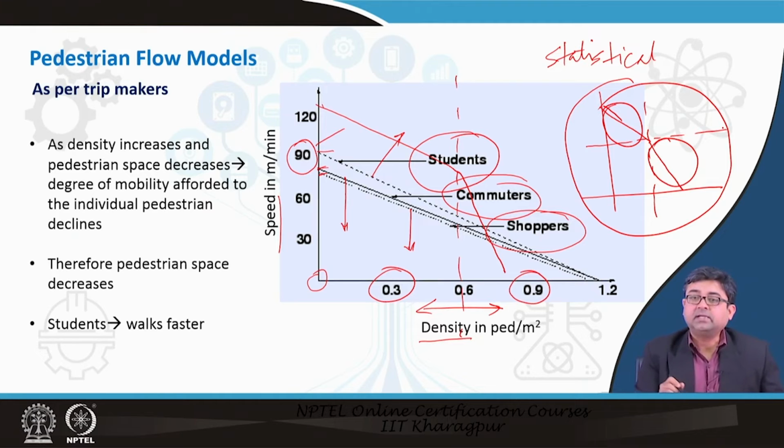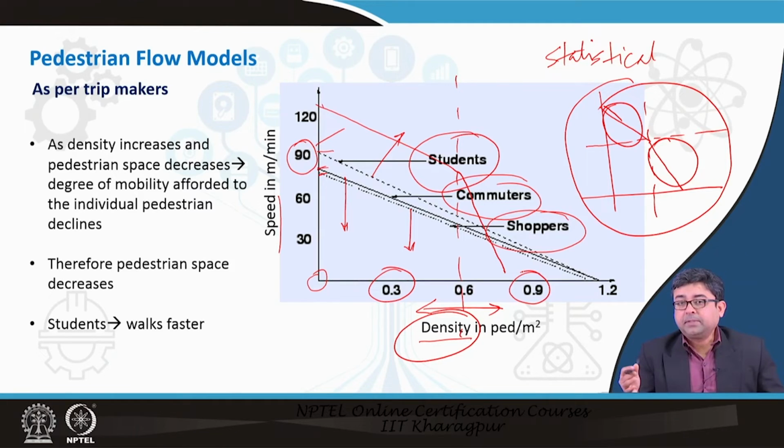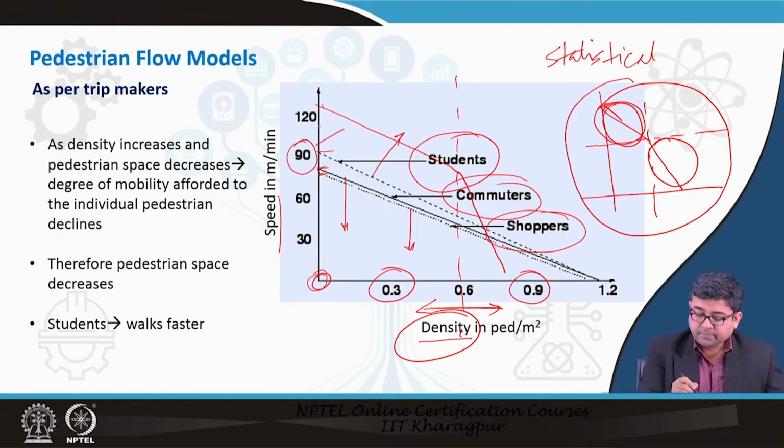So, there is some density cutoff or threshold beyond which the footpath or the sidewalk becomes congested, right. As the density increases, it becomes congested. So, in congested flow, people's walking behavior changes vis-a-vis their behavior under uncongested situations. The top part usually is the uncongested situation, because here the density is 0, and so you can have free flow speed from here.